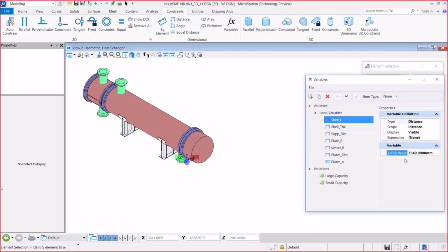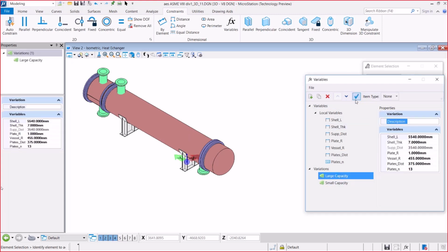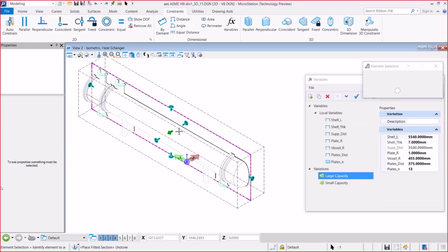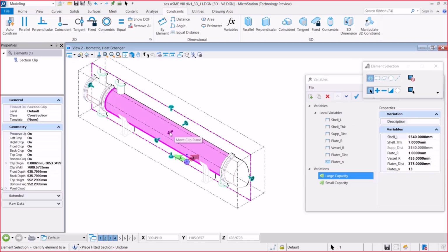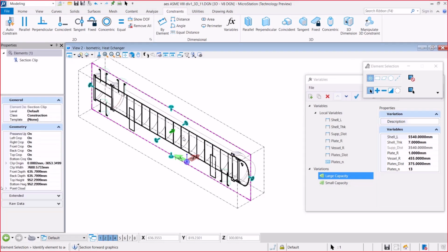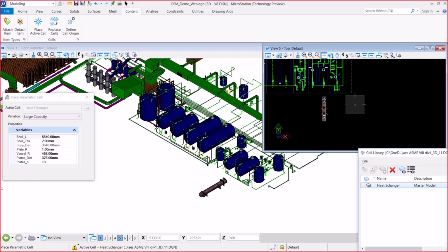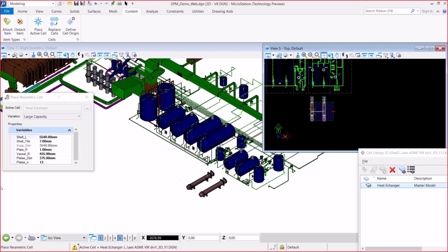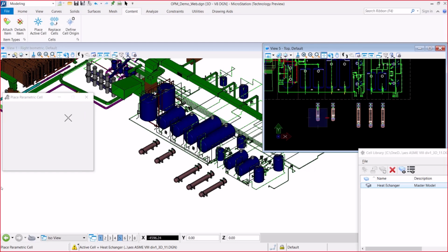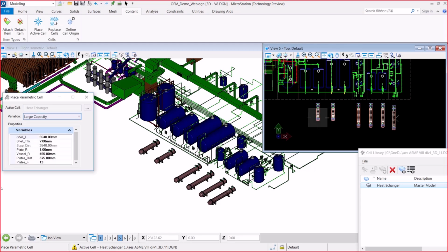This is an example of water plant equipment, and this is how we can create a component catalog, right? The idea is to provide a component catalog of parametric cells, which is geometry that reacts to variables. So both geometry and properties are always linked and connected. The catalog can be created with parameters and with variations. And the variation is based on one parametric model with a set of predefined variables that you can define, modify, and select the different variations of your requirement.